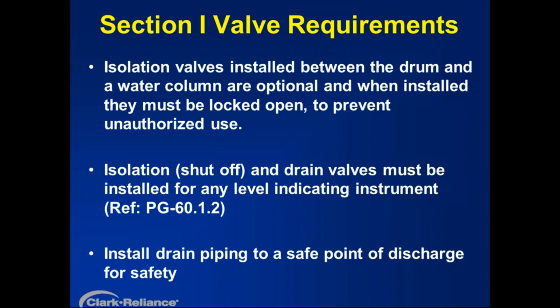And just a comment on that, a point of safe discharge is not a short pipe stub right beneath the level instrument that's almost aimed towards an operator's feet when they go to manipulate those drain valves. Usually it could be routed to a condensate return system or at least directed away from the operator who will be manipulating those drain valves.